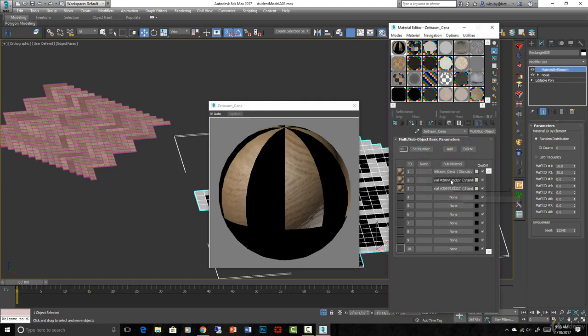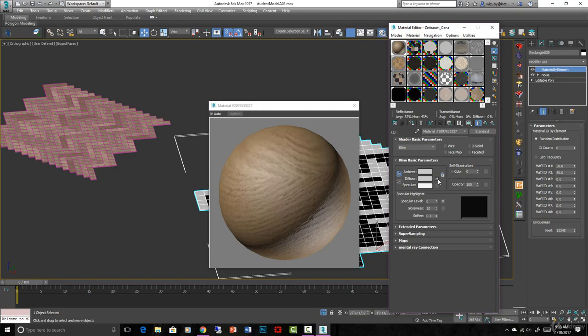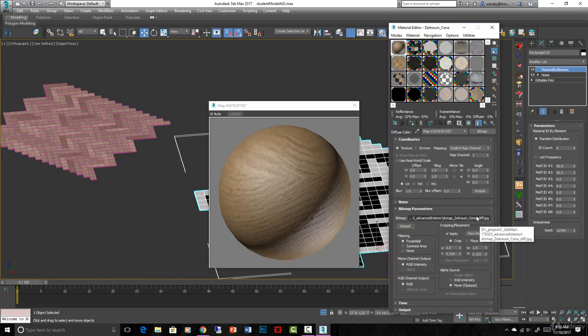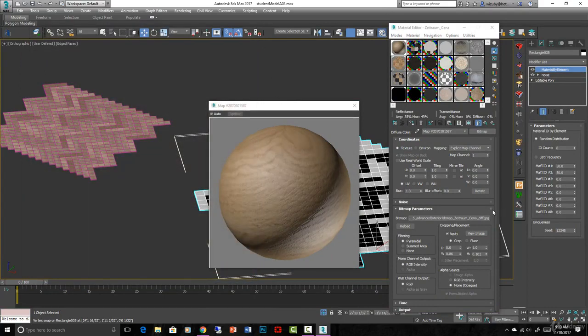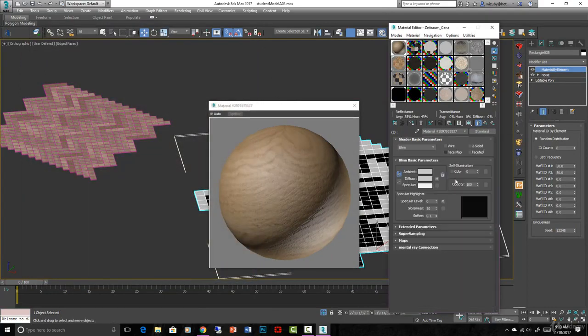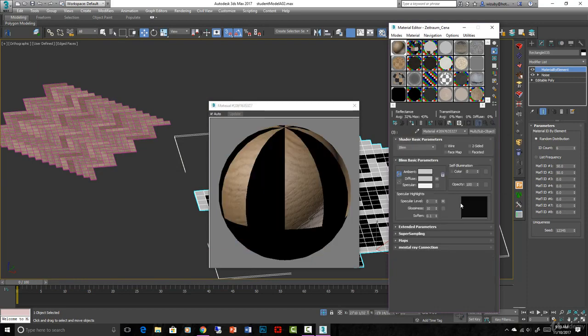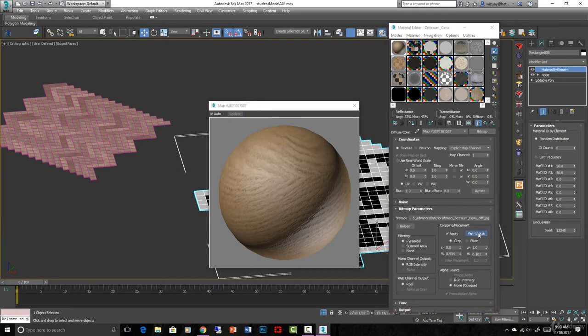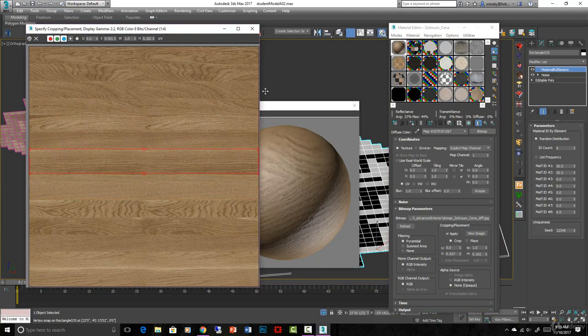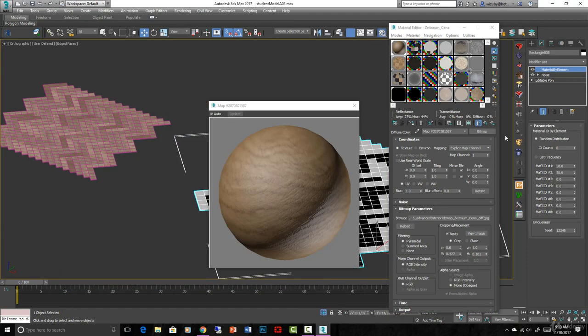And then what you do is take this one and say, okay, now let's take this diffuse and slide it up to this area right there, okay? And then on the third one, and you might adjust your reflection settings a little bit for that one too, you just make these things have slight variations and take in a different part of your wood map, or you can make completely different materials for each one if you wanted to do that too.